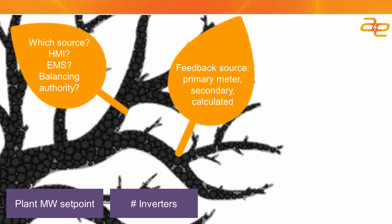Or can you aggregate the information that you're getting from all the inverters, add those up for kilowatts and kVARs, and calculate what your output from the site would be if you didn't have any meter feedback? So a decision around what to do if there's a loss in metering telemetry is an important decision in the process.